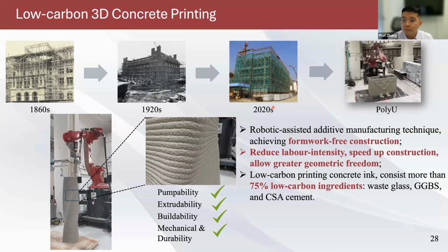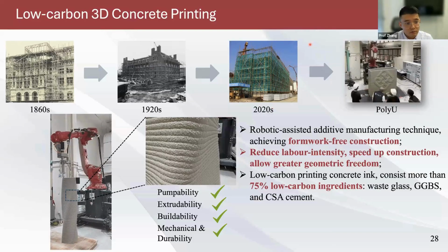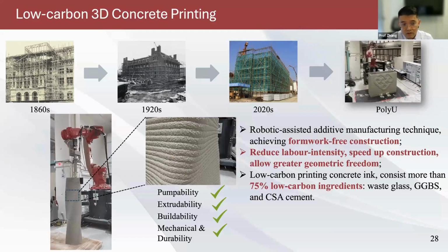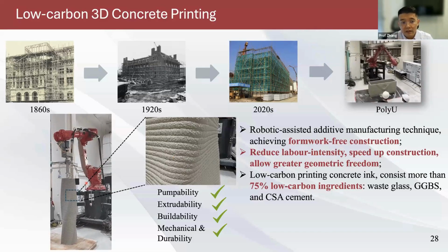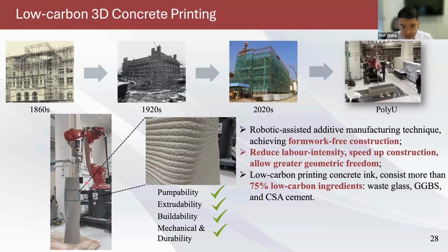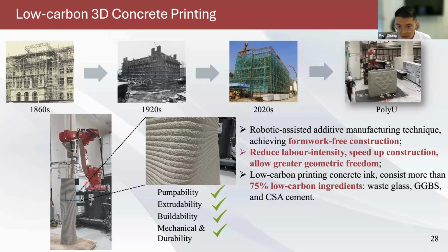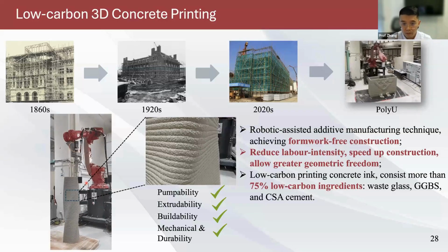So basically, the concrete will be pumped to the nozzle. This is the nozzle right here, and concrete will be extruded out and form a layer by layer structure, so you can tell the material requirements are quite stringent, right? Compared to cast concrete, where you have formwork to help keep the dimensional stability.